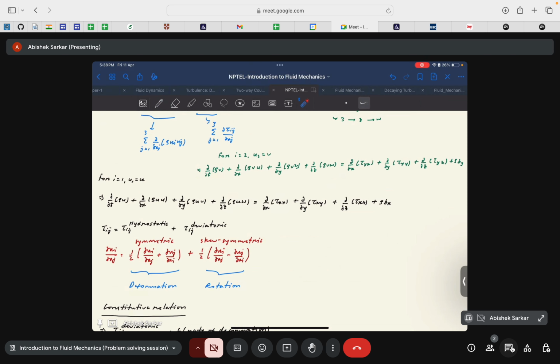But for simplicity, let us just focus on the Cartesian form of the Navier-Stokes equation till we derive it, and after the derivations we will move back to the cylindrical coordinate system when we deal with pipe flows. Okay, because the cylindrical coordinate system turns out to be the most suitable coordinate system for dealing with pipe flow systems.